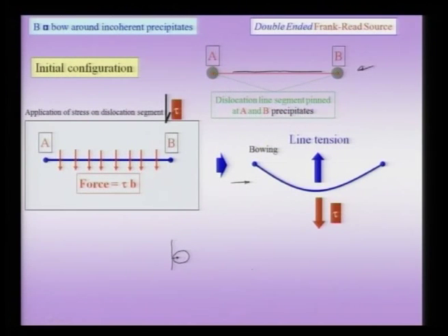That means the energy associated with the dislocation per unit length is also increasing. Of course, if I started off with a pure edge dislocation, now this dislocation would have a certain screw component to it. That means only one point would remain edge and the remaining would become screw. Or if I am starting with a pure screw dislocation, then I can similarly argue that this curved dislocation has a mixed character.